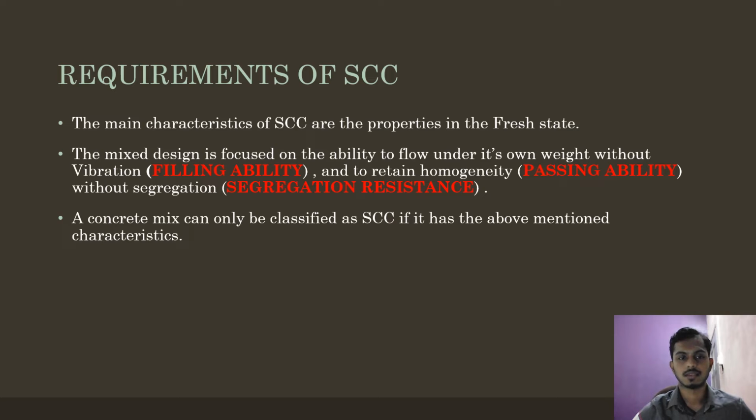Requirement of SCC. The main characteristics of SCC are properties in the fresh state. The mix design is focused on ability to flow under its own weight without vibration, filling ability, and to retain homogeneity, passing ability, without segregation, segregation resistance. A concrete mix can only be classified as SCC if it has the above mentioned characteristics.